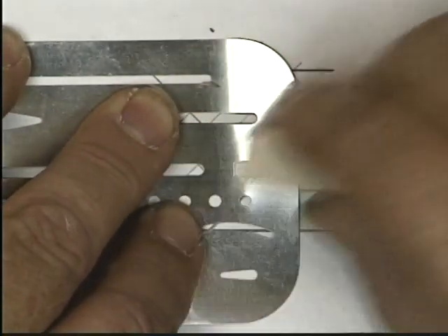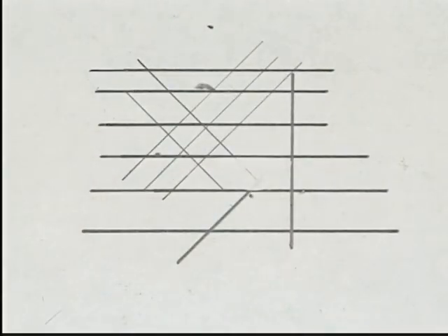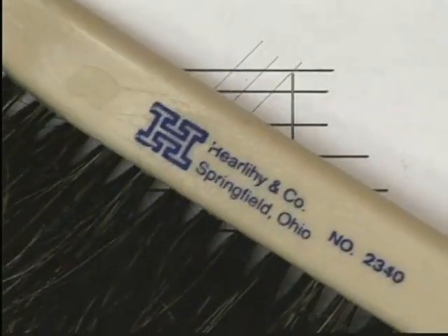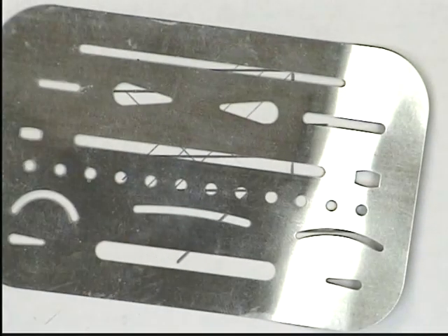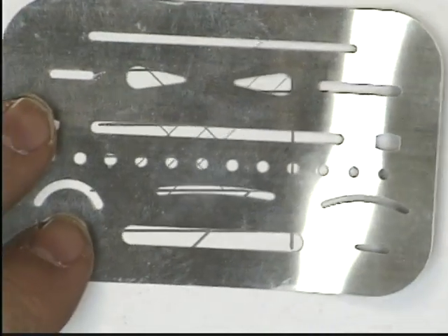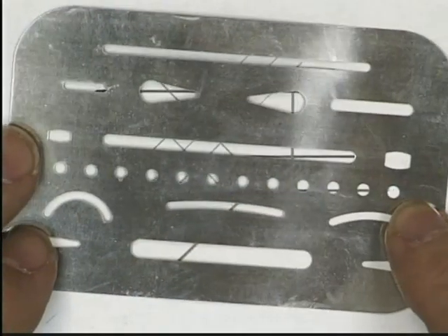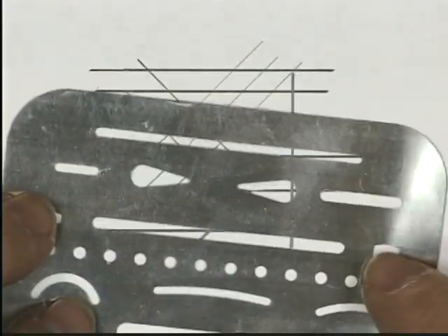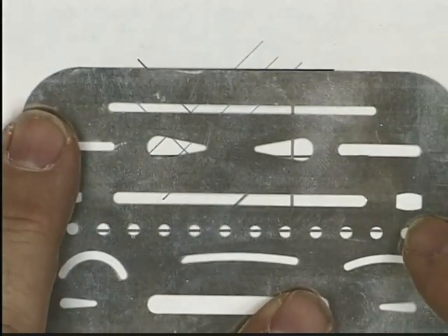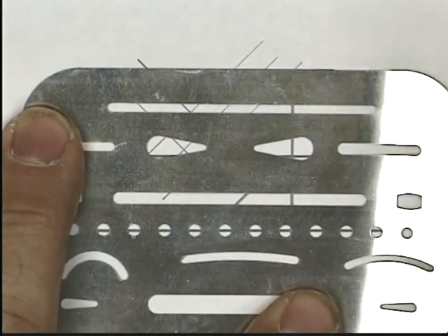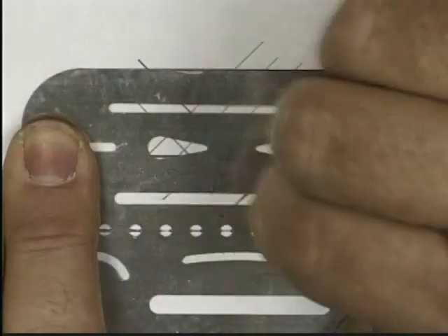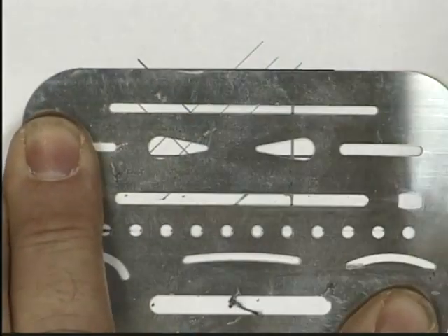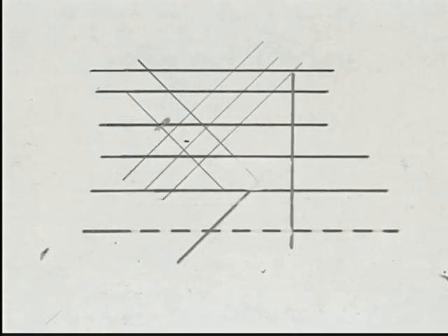Now, you get some of this eraser dust on your drawing, and you'll want to whisk it off with one of these drafting brushes. By the way, this erasing shield, you might have noticed, has this one pattern of holes all the same size all the way across. Why would they put so many holes the same size, you might ask? Well, watch this trick. I'm going to line this up with one of my object lines. I'm going to rub pretty hard across there. Ta-da! Instant dash line. That's one way to make a nice uniform space dash line with hardly any trouble at all.